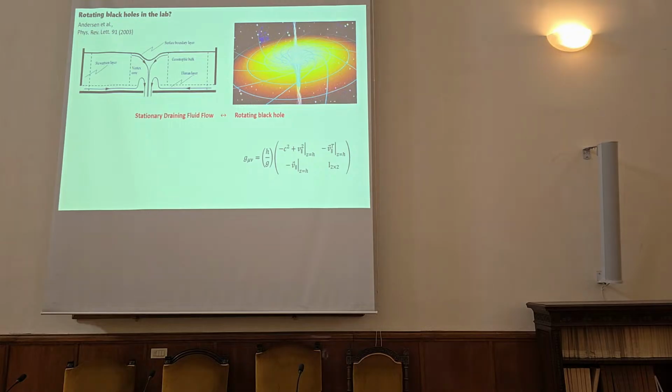If you look at this, a recirculating flow, so a stationary flow that has a sinkhole in the center, the flow behavior is very unexpected. You have a vortex core, and you have a bulk flow around. And in this bulk flow, nothing is draining. So how does it drain? Well, it drains through the boundaries. It drains through the top, and it drains through the bottom.